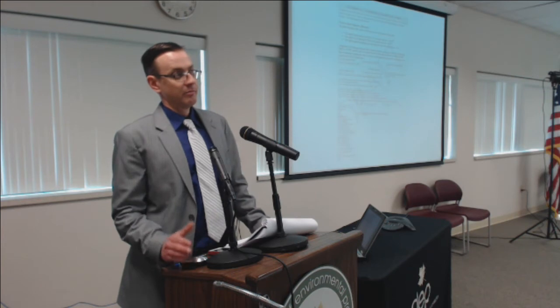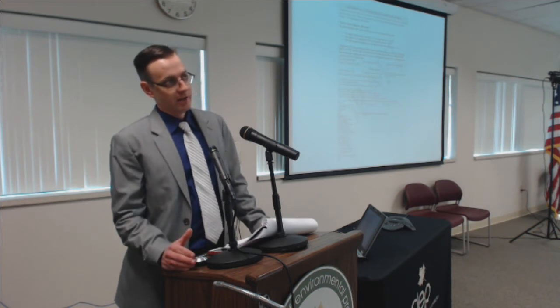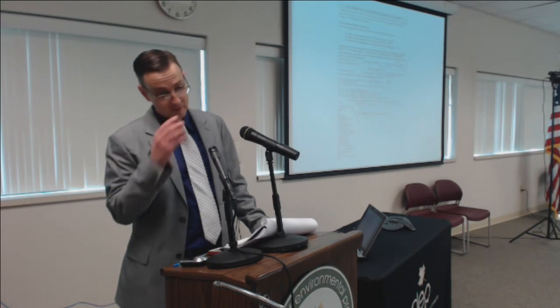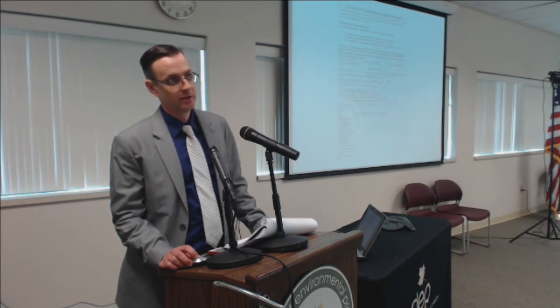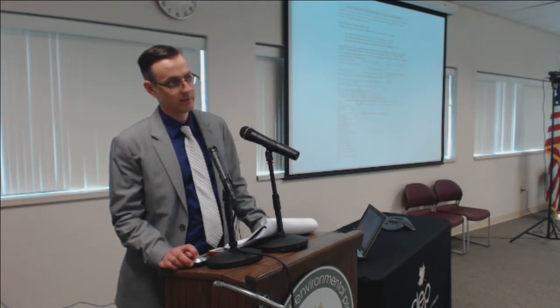And so if you're going to take that capture efficiency, and you're going to have a control device, carbon absorption or flare or whatever it is that you may utilize, then you're going to apply that control device efficiency to the capture efficiency. So the example this morning, if it was 70% capture and 98% control, you'd look at that 69% overall reduction.